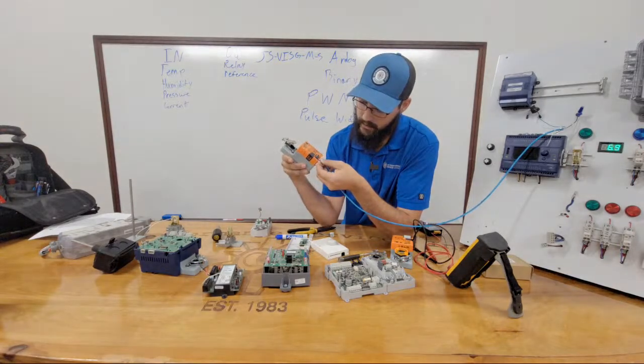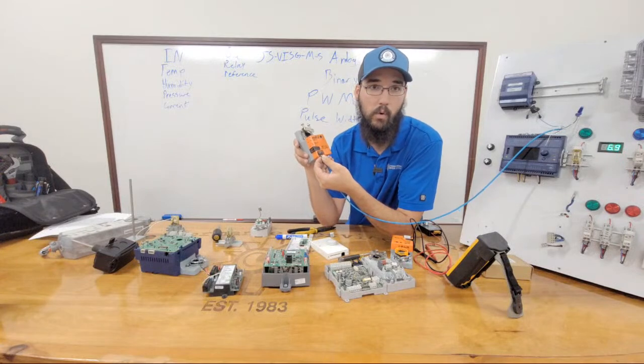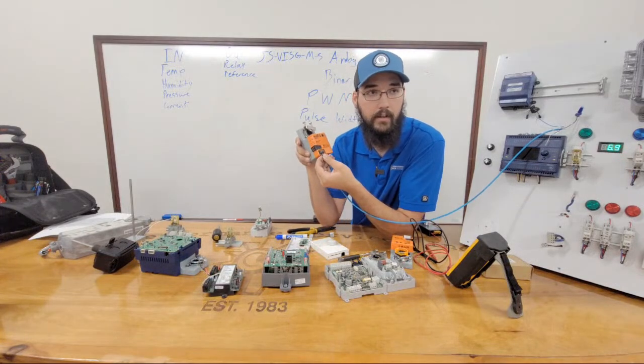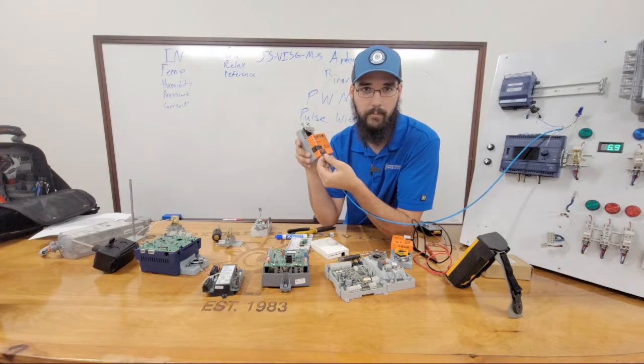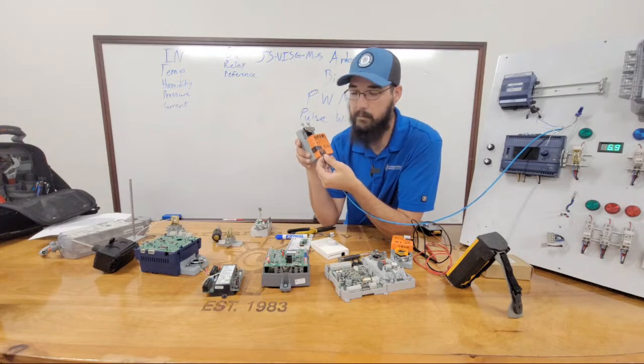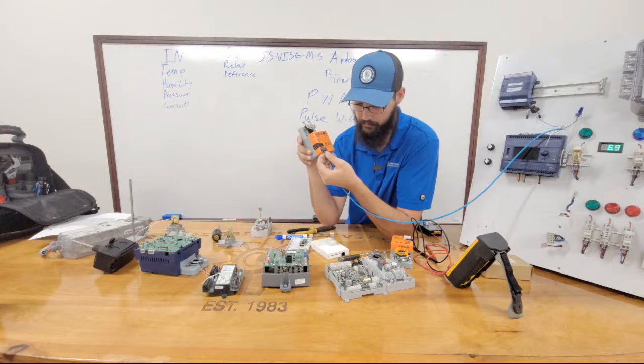Now, let's say I opened it too far and I want to close it and I want to turn counterclockwise. Well, then I go from 1 to 3 and just give it 24 volts through my little DC relays or just my little cube relays. And now I'm spinning the other direction. And it's literally quite that simple.